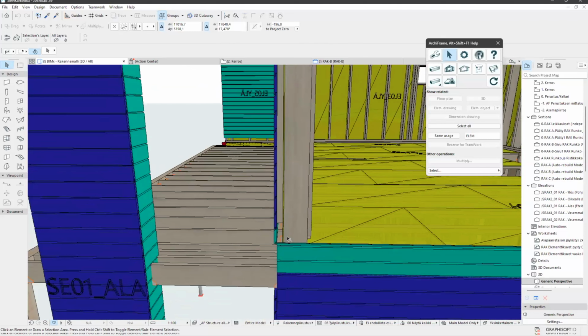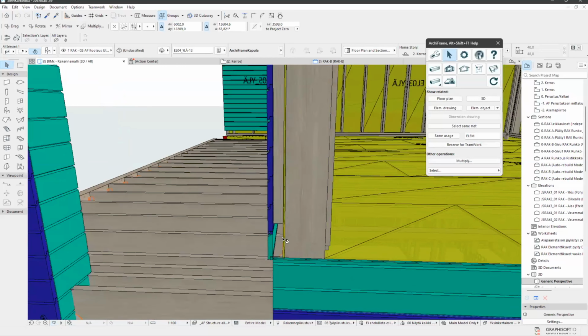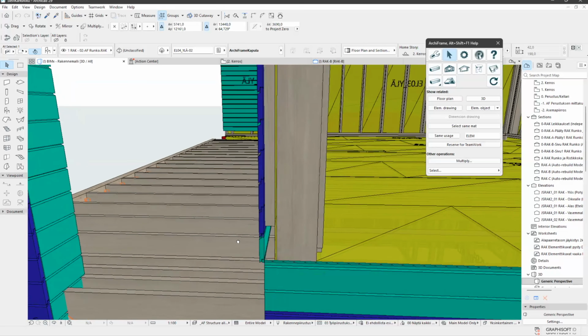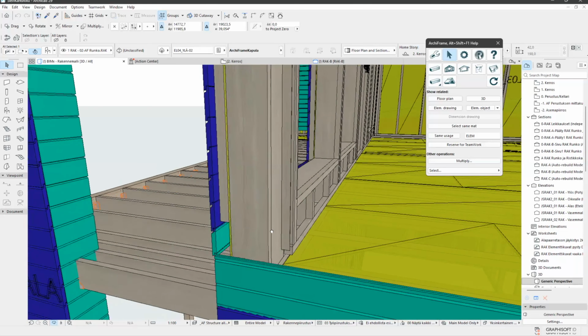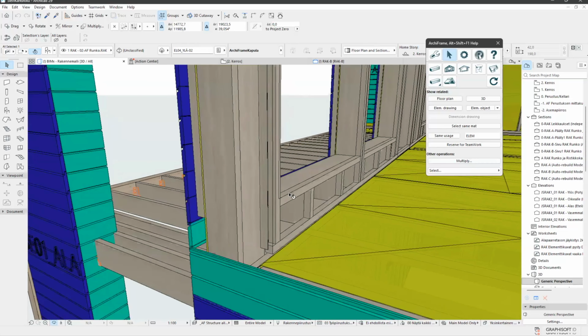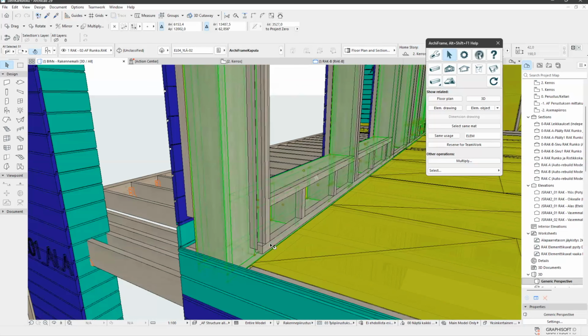Then we have the airspace between the windshield board and the cladding, and then the main framing. And I don't know if this is a Danish way also. So you have the main framing, and then very typical for Finland and Sweden, maybe also Norway, to have an additional layer for insulation and installing electricity. That seems right. Yeah.